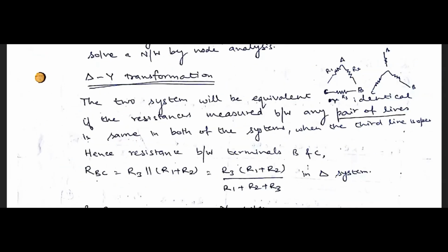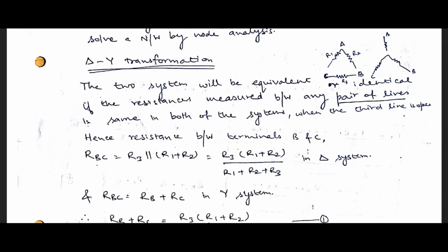When we are doing this, the R1 and R2, these two resistances are pulled away from R3. So R1 and R2 are in series, and since it is disintegrated from R3, the series combination of R1 and R2 will be in parallel arrangement with R3. Okay.